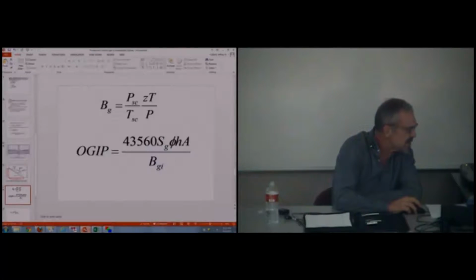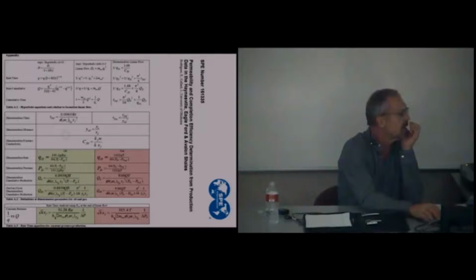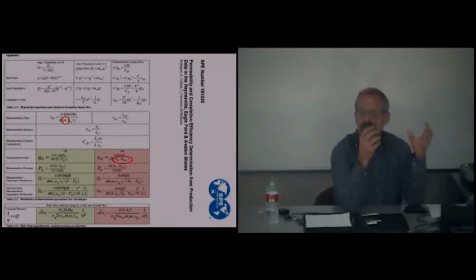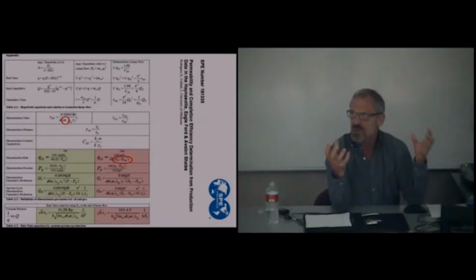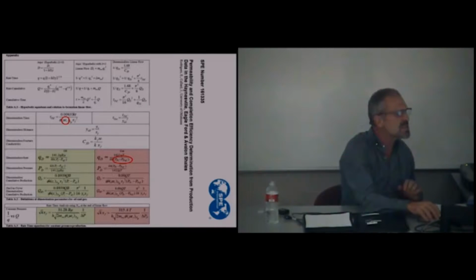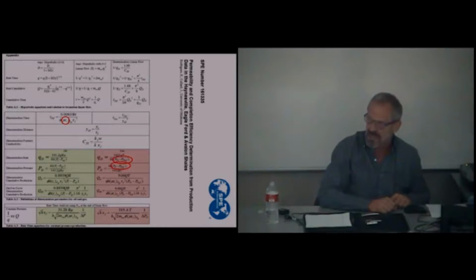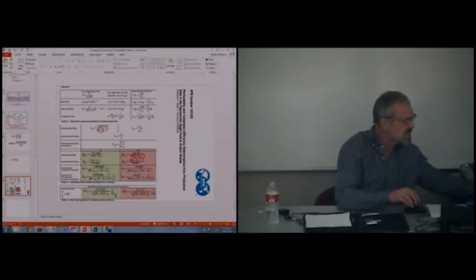But if I'm doing dynamics, not that one, but that one, where I have the pseudopressure of the external or initial pseudopressure minus the bottom hole flowing pressure, okay? That's what's going to drive my dynamics. And that same equation is in Chapter 9 in transient rate analysis and in Chapter 6 in transient pressure analysis.